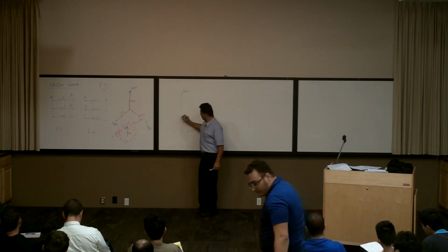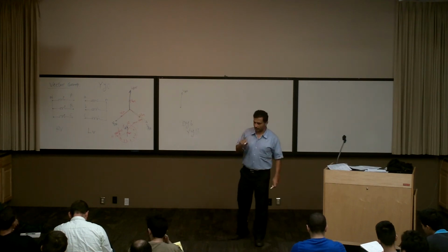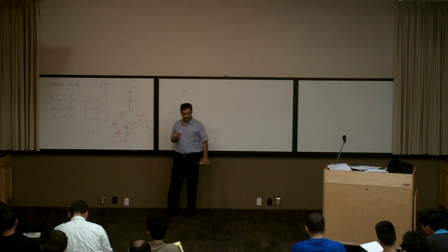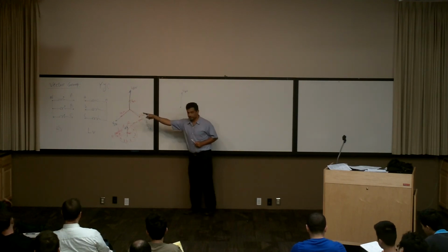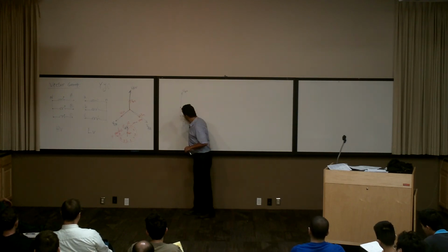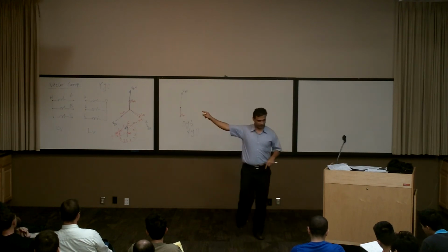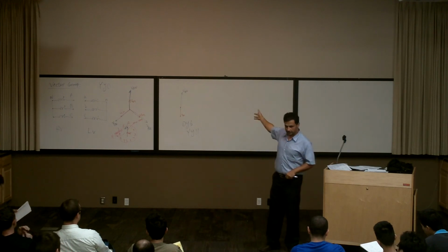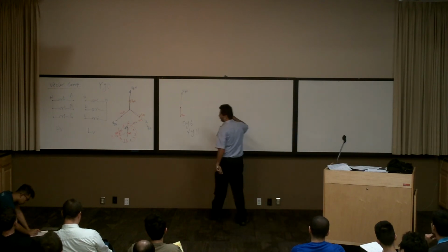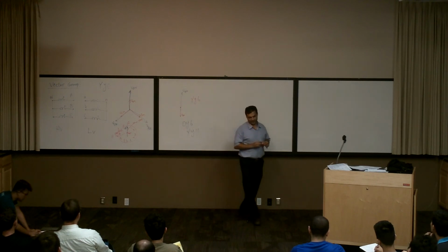And I'm not going to draw all of them. I need only one, I draw only phase A. Where is the small van in this case? It's the opposite of that one, because I changed the dot, right? It's opposite. What time is it here? 6 o'clock, right? So the vector group is Y6, right? Let's make it a little bit more complicated.